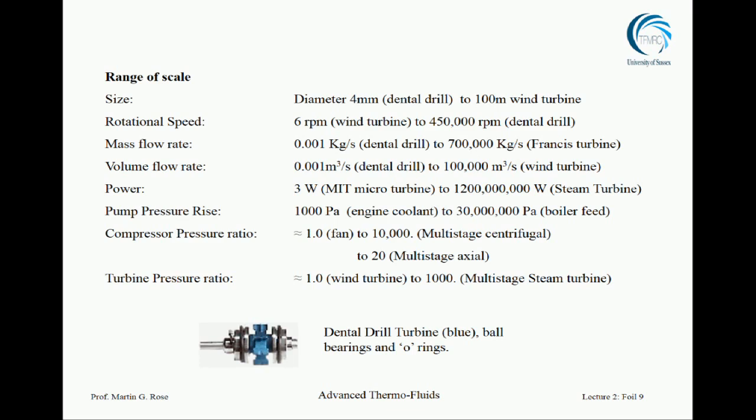Pressure rises in pumps. If you look under your bonnet at the engine of your car, you've got about 1,000 pascals. That's 1% of atmospheric pressure rise in the water pump. It's enough to make sure that the water goes round. There's also a thermal siphon which helps it.